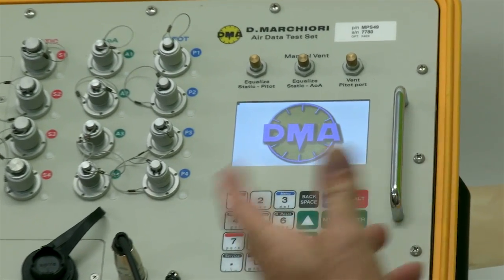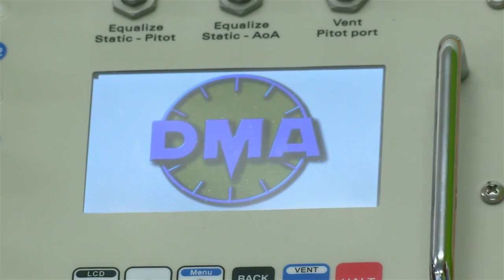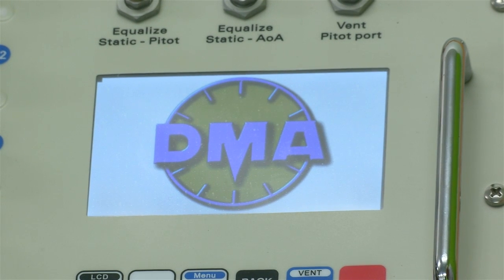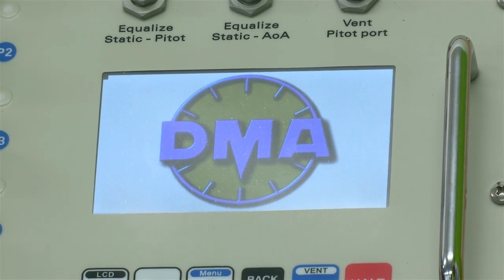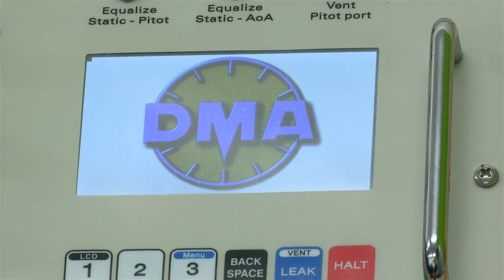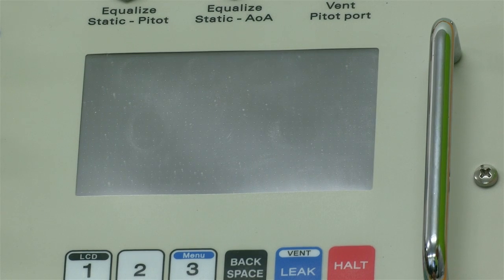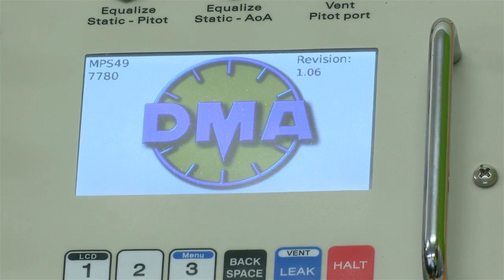We'll show how many running hours there have been for the internal pumps, and then we'll go through a startup procedure in terms of taking the instrument down to safe ambient values before we start. Well, we almost do. We have 3 different startup procedures. One, it will come straight online if we have a situation where we're very close to ambient.